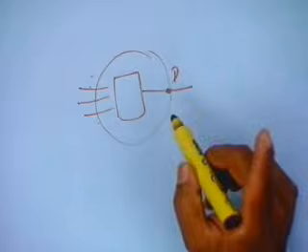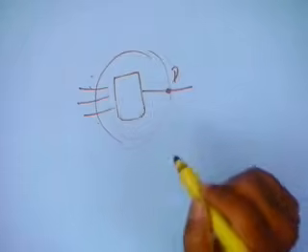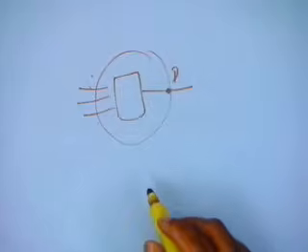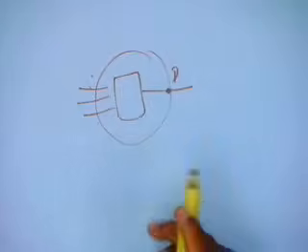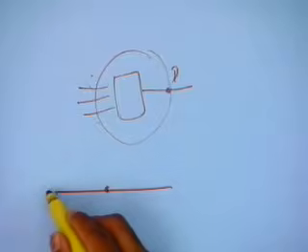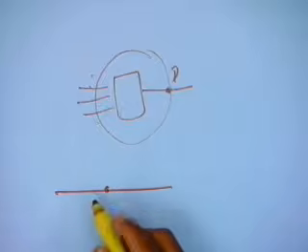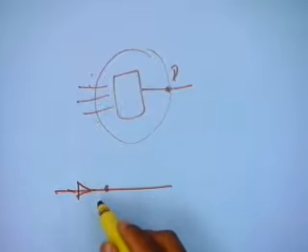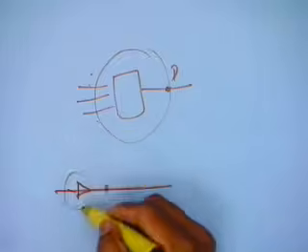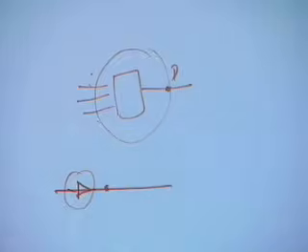So when I choose a PDCF for this gate, whichever circuit element that is there. If I am doing a stuck-at fault at a primary input, what do I do? You can just assume that there is a buffer which just follows the input and use the PDCF for this.